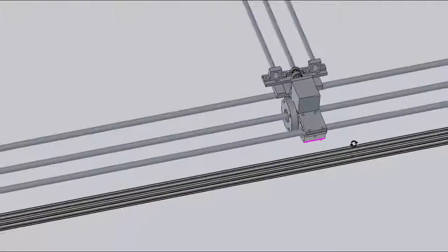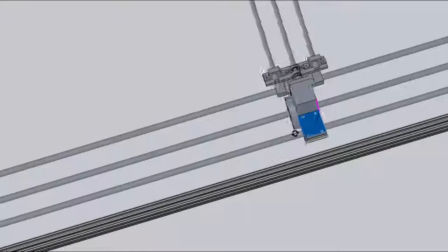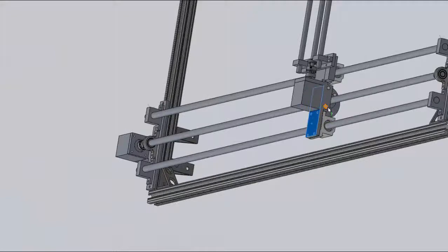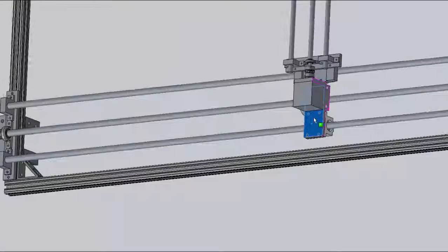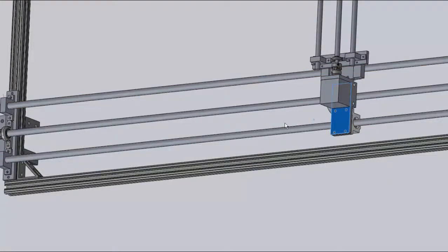On the lead screw we have mounted another 3D printed part, the large nut connector, which is mounted on 2 linear bearings. Underneath the large nut connector is a nut on the lead screw, so when the lead screw turns, the entire platform moves down the lead screw and these 2 supporting guide pins.